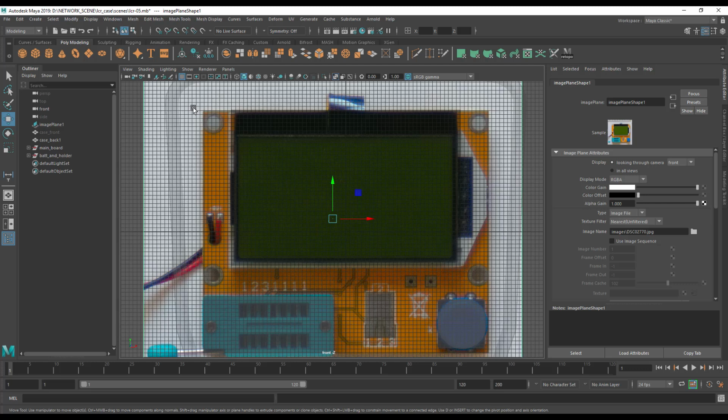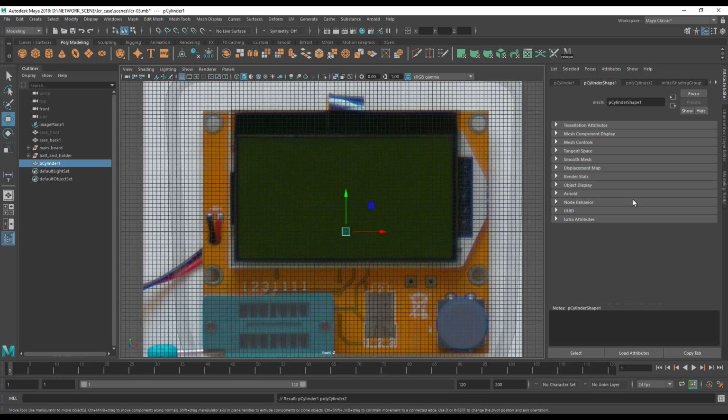Now what we need to accomplish is to drill 4 holes in our circuit board, and we need to drill them at a fairly accurate size. So I'm going to put an M3 screw through this hole, so I want a 3mm hole. Really the manufacturers of this board will probably have this hole slightly bigger than 3mm, but let's test that.